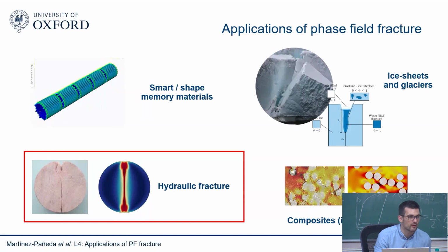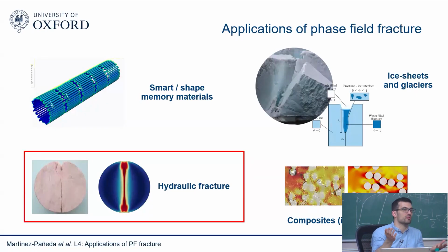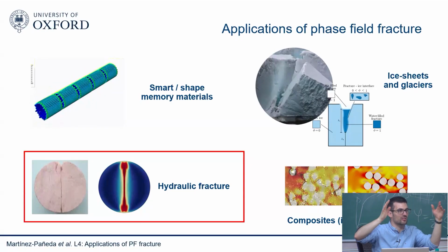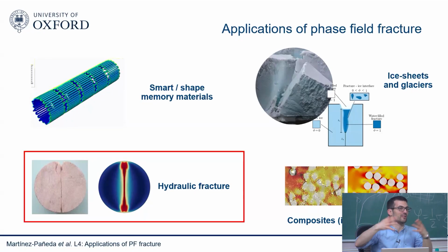Yes, so it's a linear elastic material that undergoes creep at some point. So when people use linear elastic fracture mechanics, they need to pick a Poisson ratio to calculate the stress intensity factors and so on. So they normally will pick the one of ice, which is 0.35.